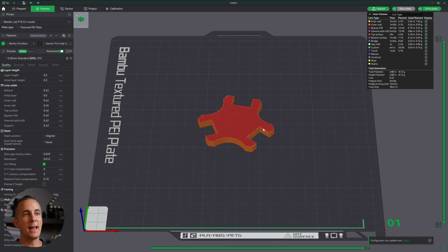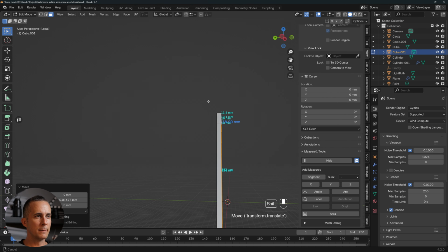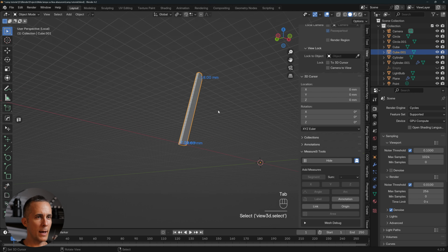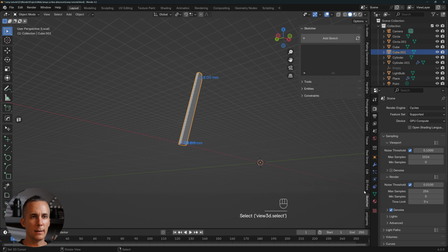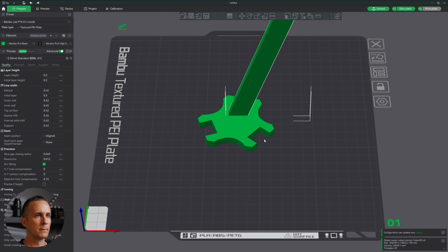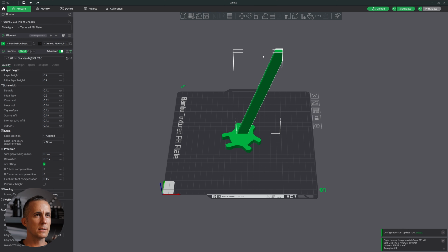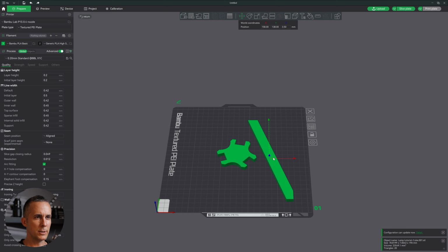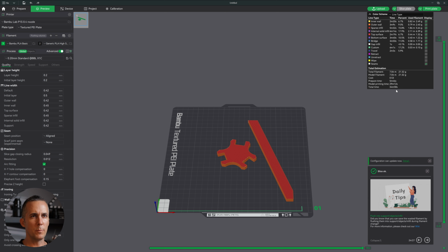And then I will also do the same with the legs. Like that. That's perfect. And I will also export this as STL. So 3D print, export this, go back to my slicer, and yeah, this is how it looks. I will go with this, and let's go to rearrange it somewhere here and slice it, and everything will be done in 34 minutes.